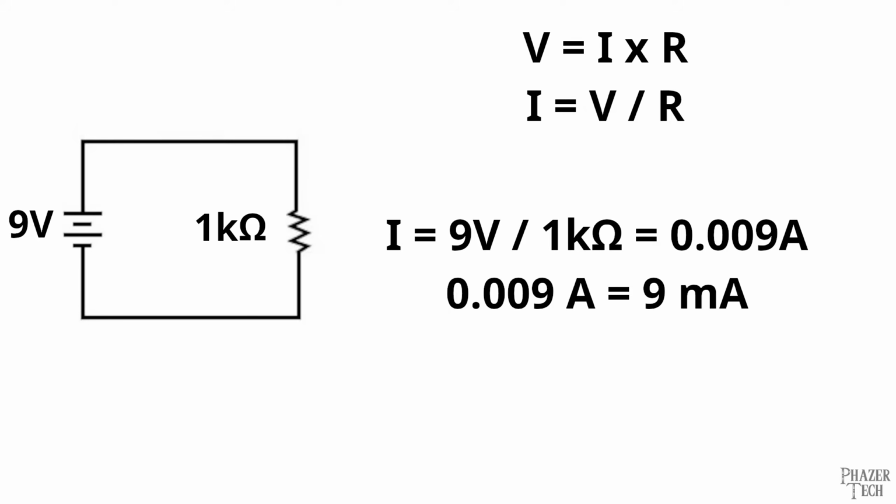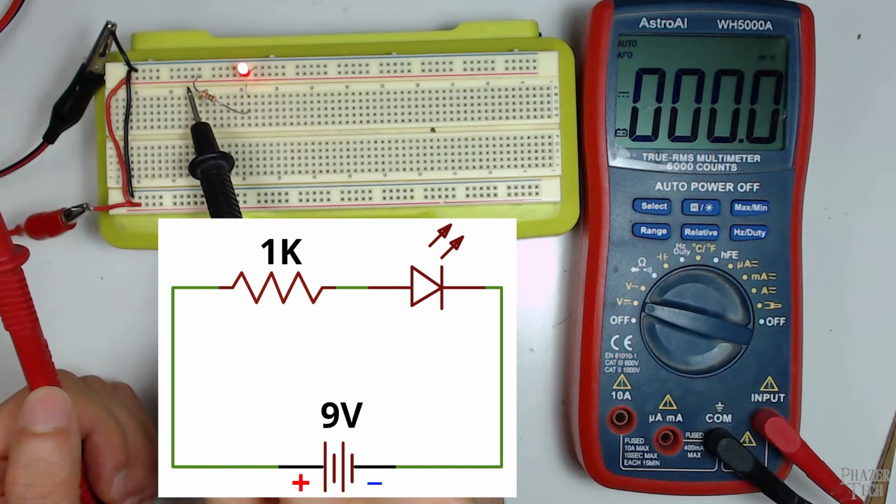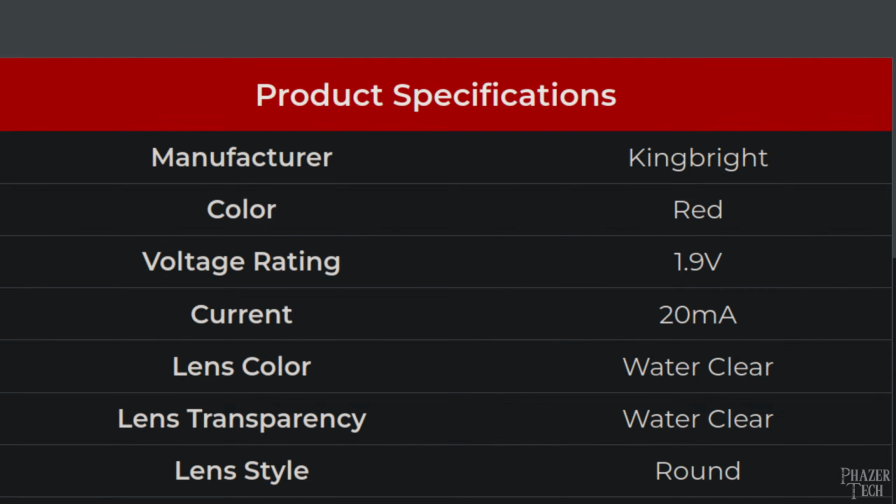You can see how higher resistance values lead to less current going through the path for a given voltage. Now let's do an example of how resistors can be used to limit the current. Let's take a look at the simple LED circuit I showed in the last video and explain it in more detail this time. The resistor here is acting as a current limiting resistor in order to protect the LED from too much current. Now, LEDs are actually a type of diode, but I'll be explaining diodes in more detail in a future video.